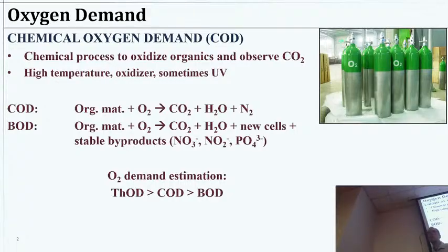Sometimes we use it to test to see if, let's say, our landfill is leaking, the leachate collection system perhaps has a problem. We can find pretty easily whether or not there's landfill effluent, landfill discharge, contaminating some water by checking this parameter. And you just send it to a lab, run it, takes 20 minutes or something, you oxidize, and you learn your result that same day instead of 5 days later. So this type of thing is used with some frequency in some fields.